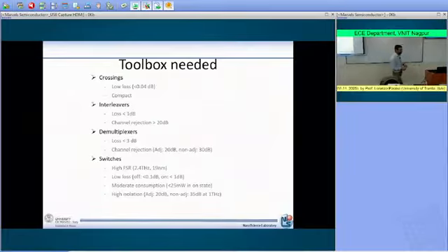And in order to avoid this, I need to have a free spectral range that is larger than the overall span of my lambdas. Meaning that I want to have a free spectral range that is something like that. Okay? In this way, I'm sure that when I'm moving this resonance here, I'm not affecting lambda 12. And this is the reason why I want to have a free spectral range that is large enough in order to accommodate all the different lambdas.